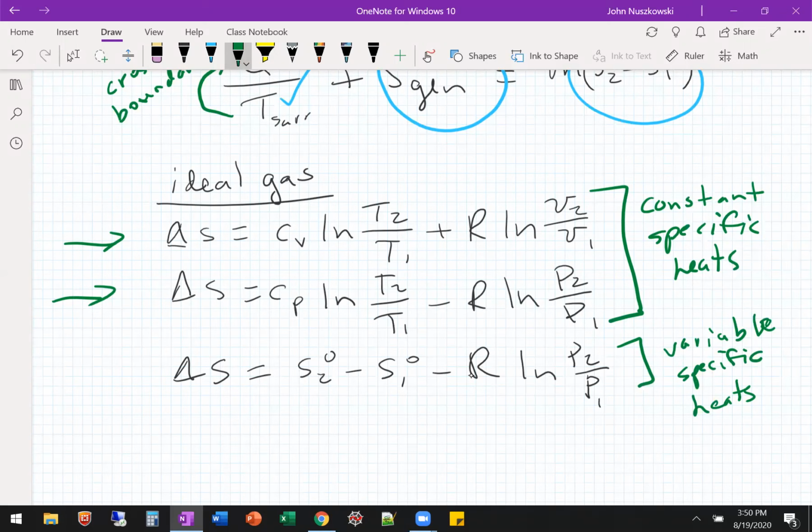So I got the second equation. There's actually no wrong answer on this one. Okay. So you are right, or the first one is also right. It just depends on what you have. We were given T1, we solved for T2, so we could use either of those. And then we're given pressures, okay? So we could use the second one, right? We have temperatures, we have pressures, we have to go get CP. What if we use the first one with CV natural log T2 over T1? What happens with the natural log of V2 over V1 in our problem?